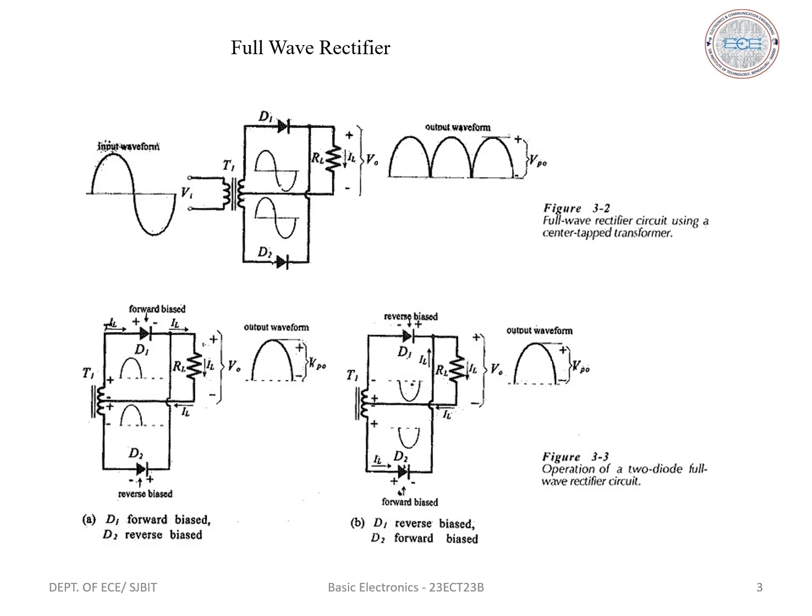Hence, we get the output across the load resistance RL in the second half cycle of your input signal also. Hence, the current flows through the load resistance RL in both cycles of the input AC supply, isn't it? So in both the positive and the negative half cycle, the current is flowing through the load resistance RL here.